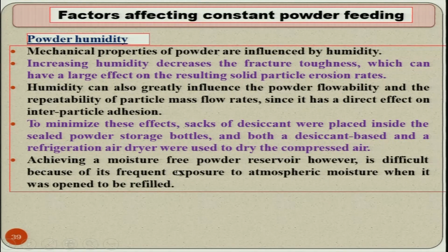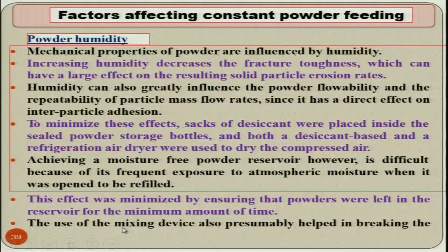and achieving a moisture free powder reservoir, however, is difficult because of its frequent exposure to atmospheric moisture when it was open to be refilled. That is right, but an attempt should be made to minimize the moisture contained, and this effect can be minimized by ensuring that powders are left in the reservoir for the minimum amount of time.